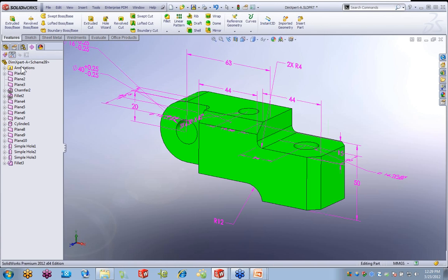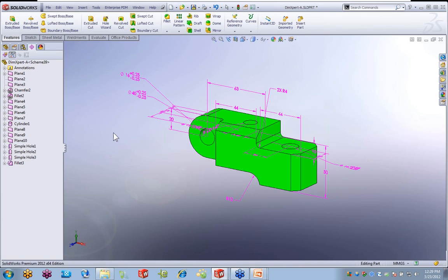it's going to go ahead and show me at the very top all the different types of features that it found. And I can click on them one by one, and they'll highlight in a darker shade of green. It found all the chamfers, it found the cylinders. Now what it also does is create annotation views. We just introduced those earlier. We have now 3 annotation views and then our unassigned items.